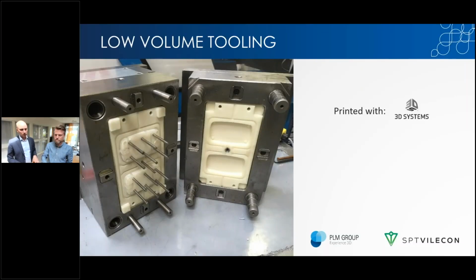This was printed on a 3D Systems machine. We did it for a Danish company called SPT Wilecon, and they wanted 200 parts, and no one in the injection molding industry would take these kind of jobs. It's too expensive to make a tool just to produce 200 parts. So we did this in plastic. The tool cost was roughly 500 euros, just below 500 euros.